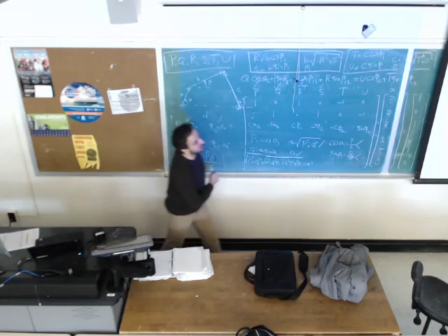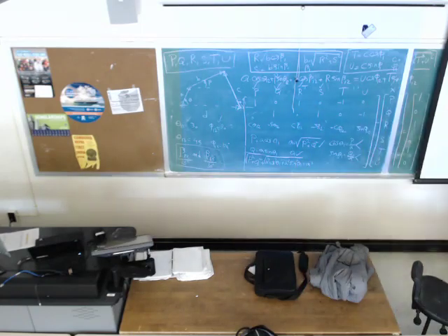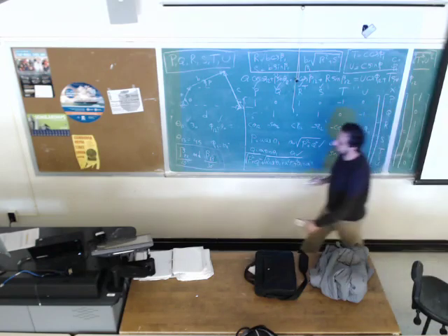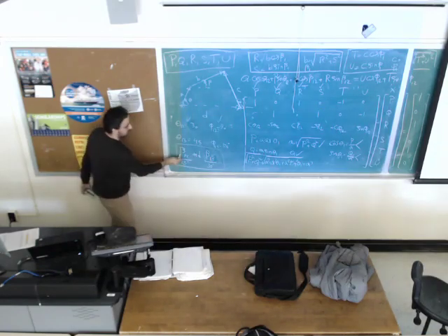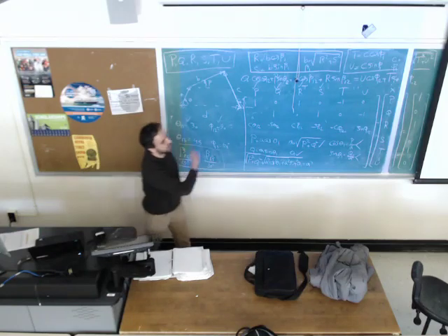The only thing that you have is free choices. I might ask you, I would like to have mu max less than 135, for example, and mu min greater than 45. After you find A, B, C, and D, if it's a crank rocker, you should find the mu max and mu min. If it doesn't satisfy the criteria, you have to change these values and try it again.